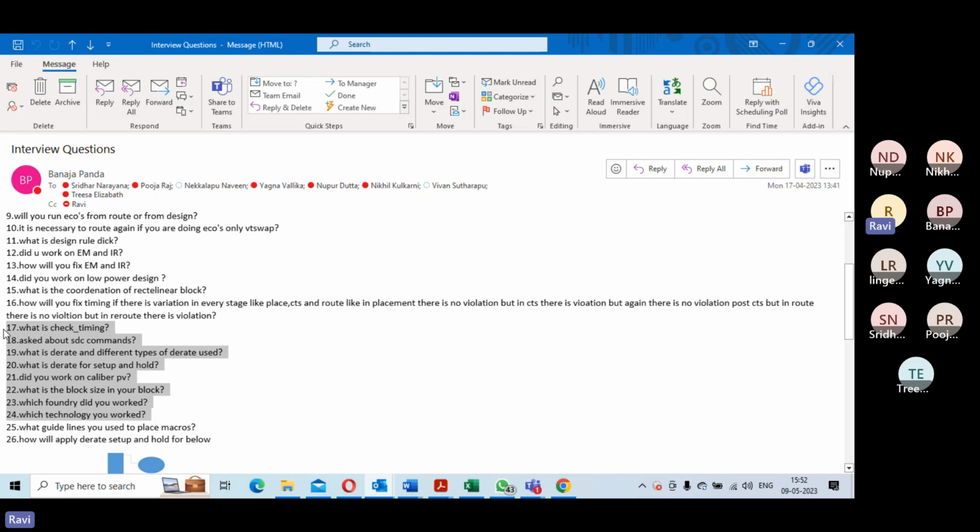So that's about input output constraining. And what about physical design constraints? You can have set max capacitance, set max fanout. These are all design constraints, set max transition, right?